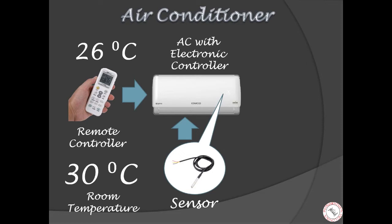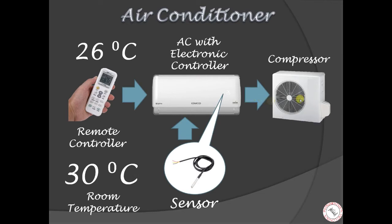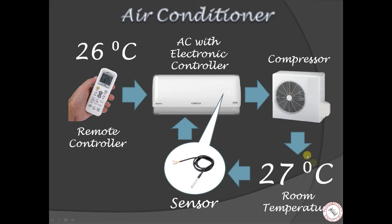The electronic controller compares the current room temperature and the required room temperature and finds out that the room temperature needs to be reduced by 4 degrees Celsius. To reduce the temperature, the controller sends a signal to the compressor to turn on. As the compressor turns on, the room temperature starts to drop, and the temperature sensor continuously monitors the temperature and sends the signal to the controller.